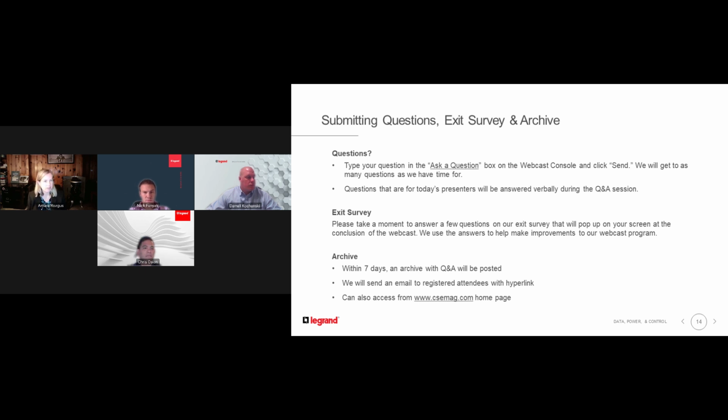Daryl, I have selected a question for you first. Kind of a general question. What is the max amp tap box available? Yeah, great question. Our typical plugins are rated up to 120 amps, and that's our standard footprint: smaller style enclosures that can fit directly above the rack. We, however, can provide plugins up to 600 amps. For circuit breaker only units, Nick's team uses those quite a bit at 400 amps for load banking and commissioning purposes. So we can essentially go all the way up to a 600 amp unit with our plug-in units.